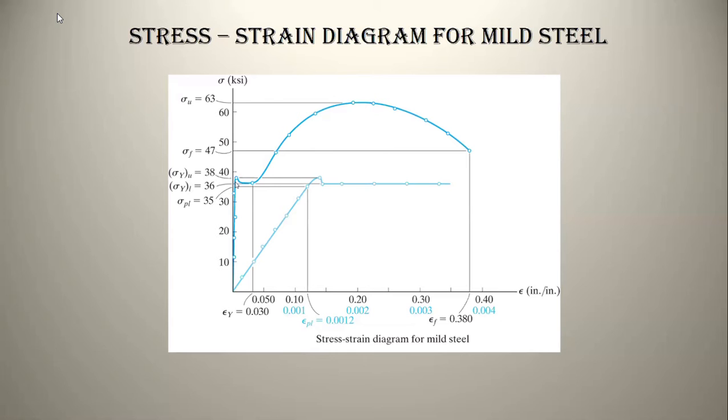So, was the yield strength the subscript U or the subscript L? Yield strength is subscript Y, this one. And then what's the additional subscript U and L? What is their difference? They're the upper and the lower limits, because yield strength starts from right here and could go up to there, and then it settles down at this point. So this is really called the lower yield strength, and this is called the upper yield strength. All right.